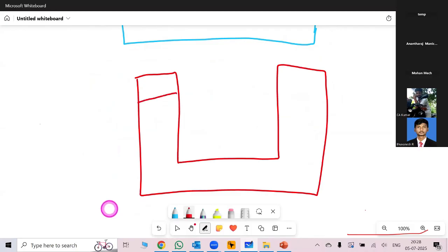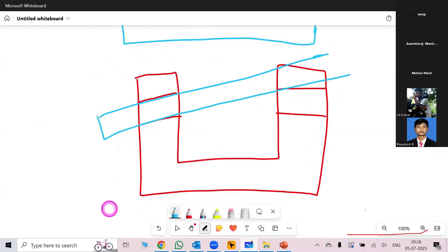This hole is slightly tilted, and this tilt would be within the positional tolerance given in the drawing. And this hole is like this. Now, if I try to assemble a pin, that pin will trace a path like this. I will not be able to assemble the part.